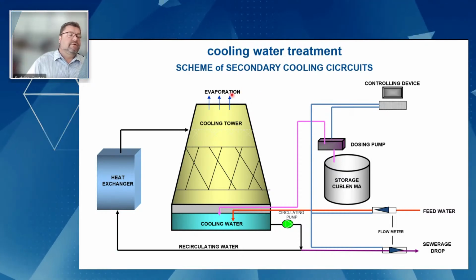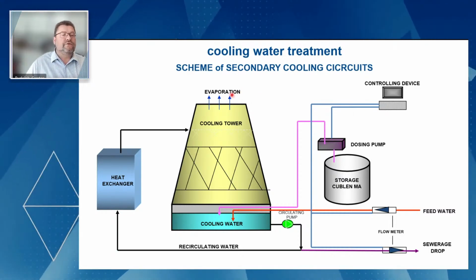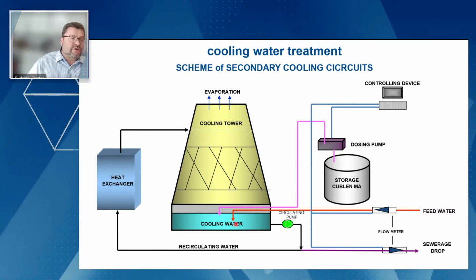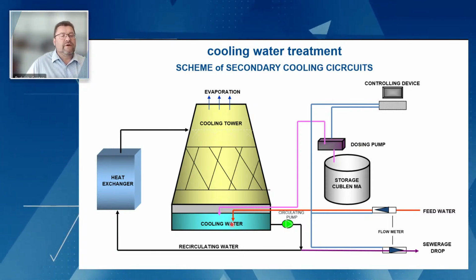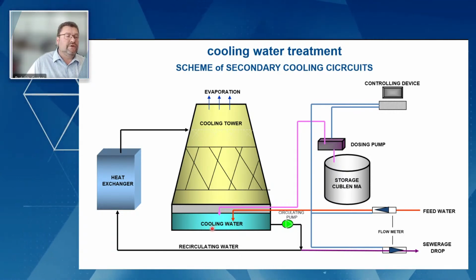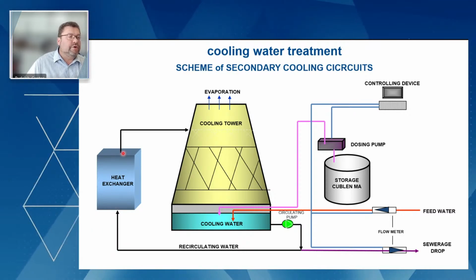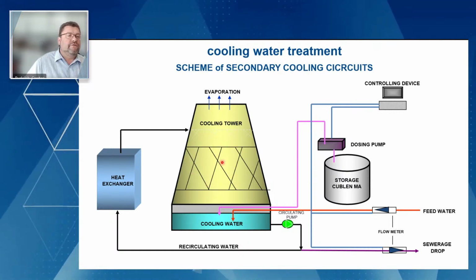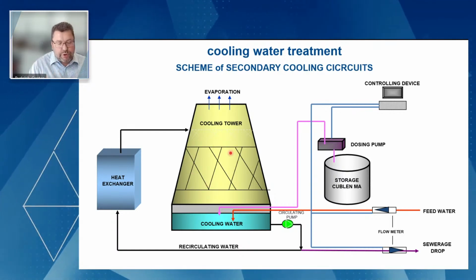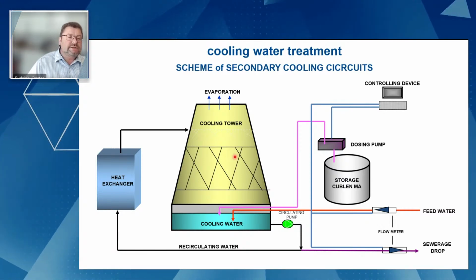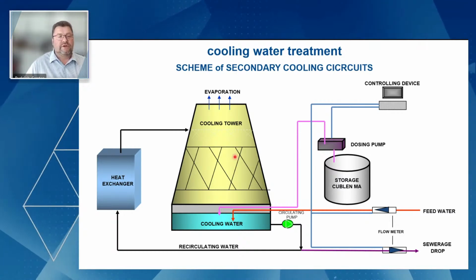For this reason, we have a concentrating of the material inside, and an antiscalant is dosed into the basin and prevents the incrustation, which mainly occurs on the critical spots. The critical spots are the heat exchanger, because this is a hot spot, and the cooling tower itself, where the water is sprayed down. And here in the installations, we have this blocking with the chalk.